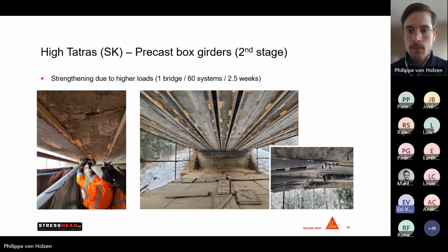Perfect. One other question. For buildings, the question is, will the PT system help the buildings for local strengthening only, or does it affect the global performance? I think, go ahead, you try, and then I'll give it a shot too. I think it depends a little bit. If we apply an additional post-tensioning force to the system, we are changing the whole behavior of the whole structure. I think the correct response is more towards the global behavior of the whole structure, how the loads will be behaved.